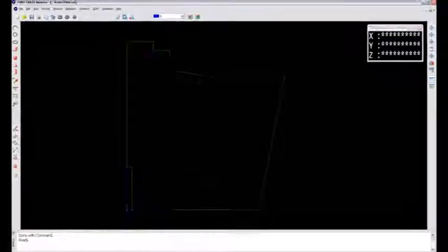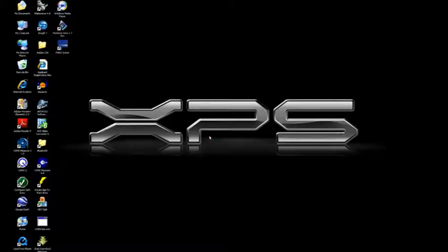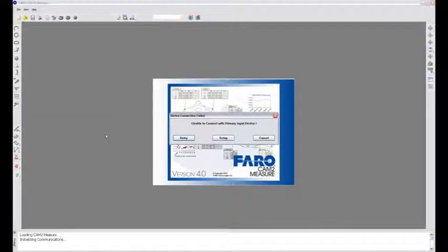Now I'll back out of CAM2, say this session was done, my client got exactly the data they were needing, and then maybe I go to another client or I do another measurement session where I'm going to do the same thing. I'm just going to export out an IGES file of a quick part that we just did some reverse engineering on. So I'll fire up CAM2 here again a second. And I've made that change in my read-write options so that my IGES Polyline data was set to no.